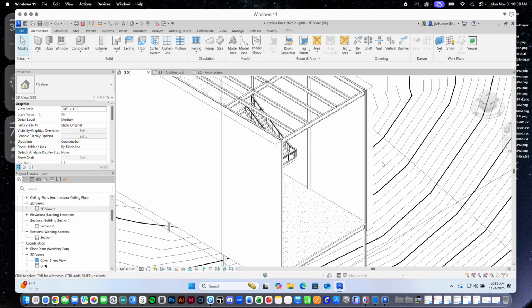There are ways to get around that. In fact, the more contemporary curtain walls are better about that. But if you start to hear the building creak and crack, that's usually expected, right? Things start to move. The building's always moving, and so it's about how you control it so that something that moves faster is next to something that moves slower, so we don't end up with all kinds of massive failures, cracks, and other problems.